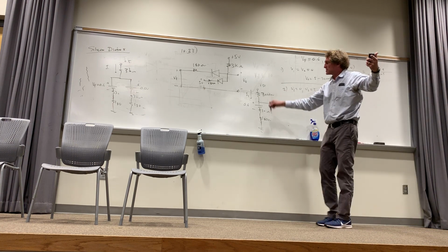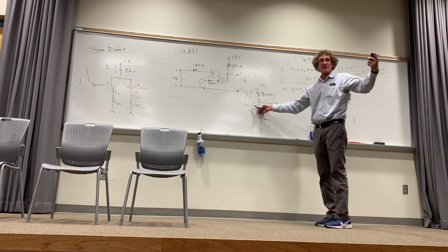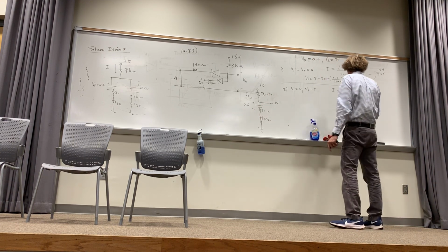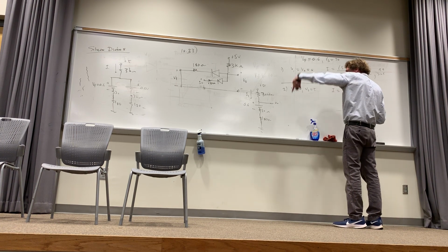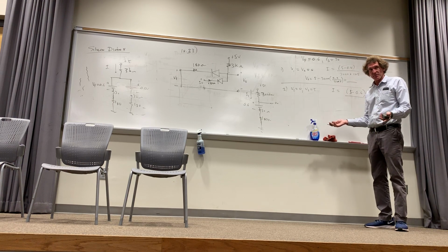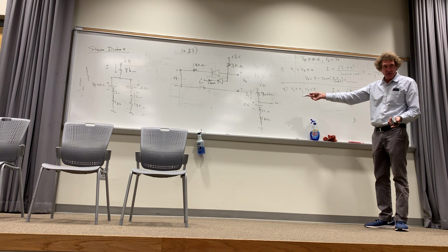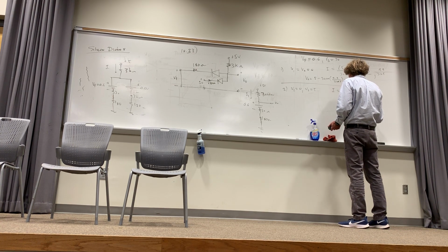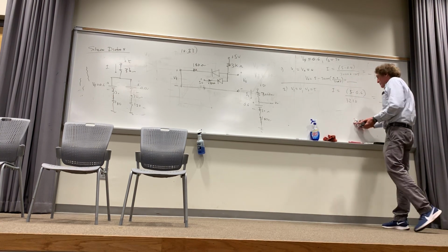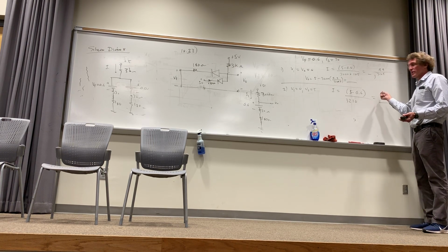Well, how much total voltage is driving current this way? 5 minus 0.6. Do y'all agree with that? So it's 5 volts minus 0.6. That's the voltage driving current that way. What's limiting it, class? The 3,000 plus 180 plus 30, right? So that's 210 plus 3,000, so it's divided by 3,210 ohms. That's the current, correct? 0.00137.